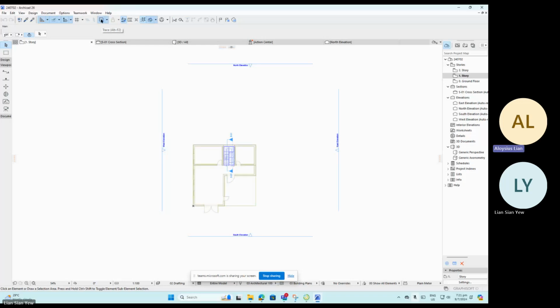And immediately you will see that the computer displays the outline of the elements that are below in a sepia color. If you were to click on alternate F2 again, or this button again, it will toggle between these two visibility states.